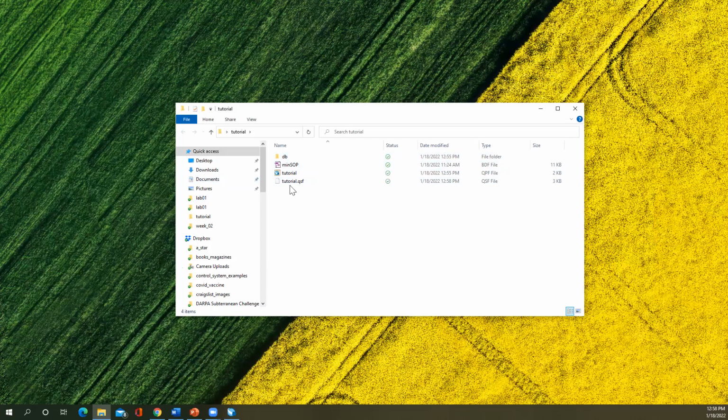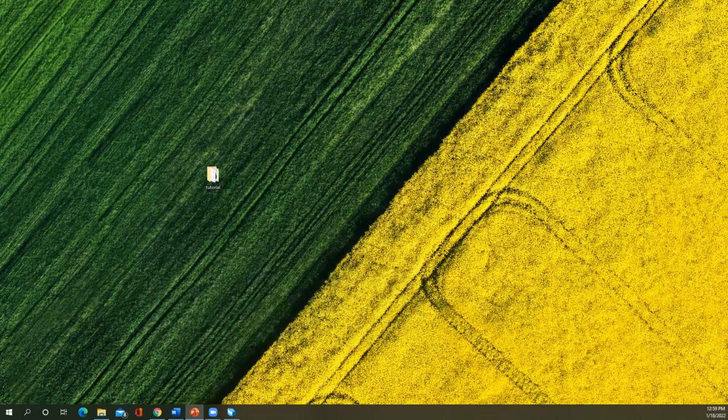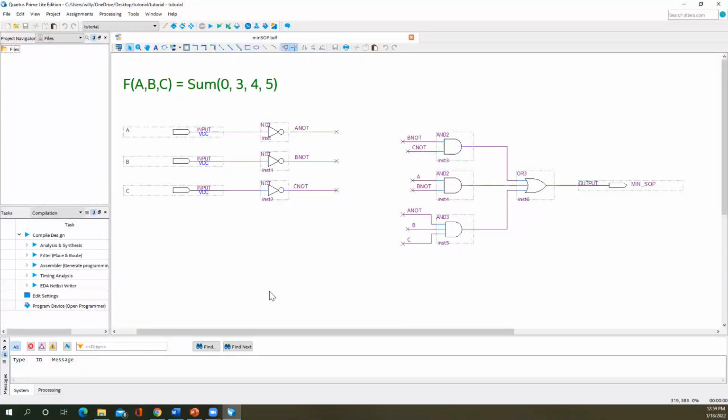And you can see then as we created a Quartus project, it created this QPF file, this Quartus project file here. It created this QSF, this Quartus settings file. It created a subfolder DB with some database information that gets updated as we make changes to our program. Those are nothing that we have to maintain, right? The Quartus project environment is creating them and maintaining them as we make changes in the environment. All right, so I just wanted to show you that even though we said remove, it didn't delete our file. All right, let's bring the Quartus project back up here on the screen.